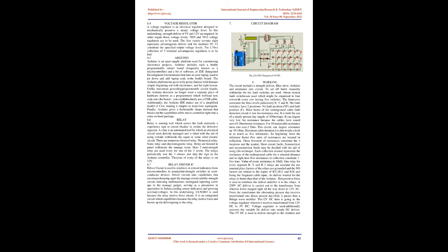LCD display. Liquid crystal displays are interfaced to the microcontroller 8051. The most commonly used LCDs are 16x2 and 20x2 displays. In a 16x2 display, 16 represents columns and 2 represents rows. LCDs are available to display arbitrary images or fixed images with low information content, which can be displayed or hidden, such as preset words, digits, and 7-segment displays in a digital clock.